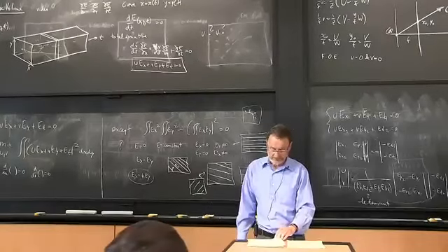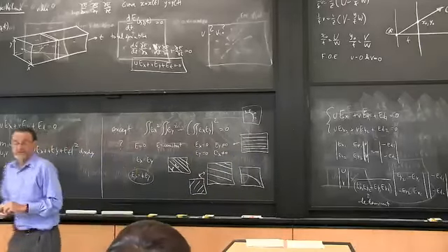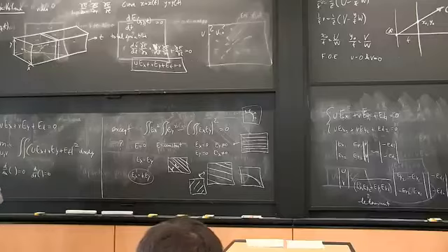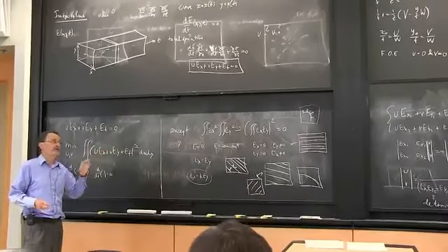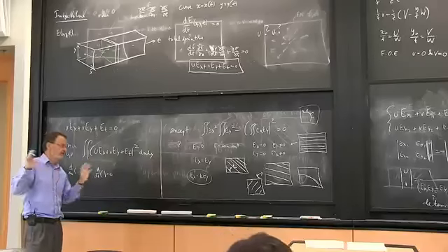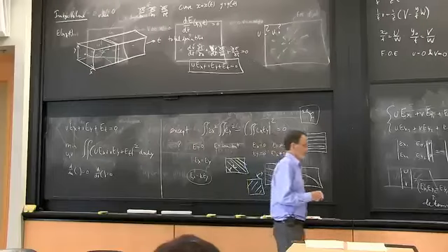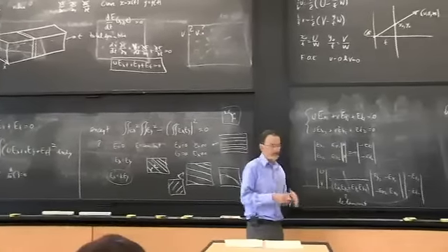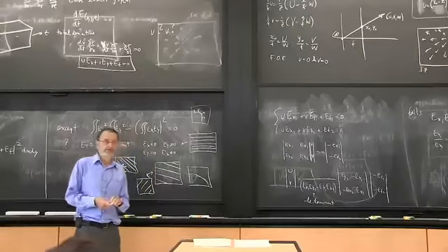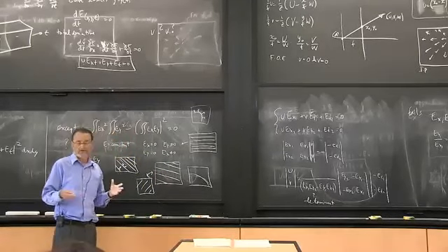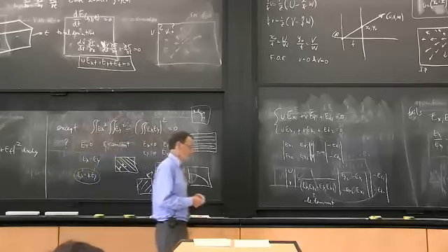What we're going to do next is talk a little bit about this concept of noise gain. So the idea is that all this time in the back, we've been thinking about, oh, we only have pixels with 8 bits and they're noisy and our calculations are going to be flaky unless this determinant is large and so on. So there's a lot of attention to not just a formula for computing the answer, but making sure that the answer is actually meaningful, as opposed to you've taken two noisy numbers and divided them by each other and the result is not very predictable.